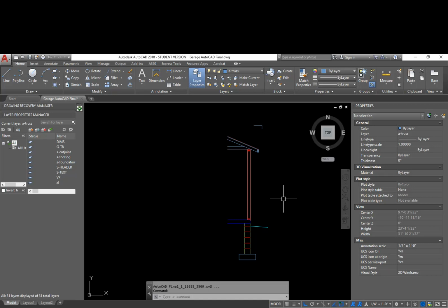scale. And AutoCAD can handle that by doing some different scales and different viewports, but it doesn't handle it real nicely. So what we'll end up doing is we'll take this drawing and block it out, make it its own drawing, and then work on that in a different location. So what we're going to do instead right now is we're going to use this wall section to basically create all of our elevations and our roof plan using orthographic projection.